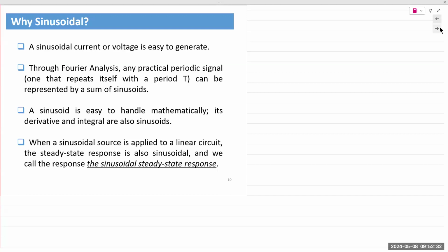That mechanically rotates the coil inside the magnetic field, and, going into physics, electromagnetism, that rotating coil generates movements of electrons that go up, down, up, down because of the magnetic poles, north, south, north, south. That's how you generate a sinusoidal waveform.